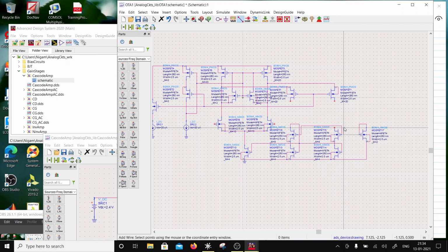Yes, that's correct. So this is driving this node. So now we are all set, and this is connected here, and this is connected here. So now I have the input currents difference, which will be generated by the input signal, will be translated to the output through 1:1 mirror, which is a folded cascode here, and then there is a high impedance node which is VO over here, right? And then this is driven by almost half the current.